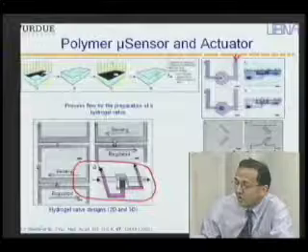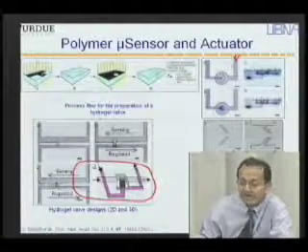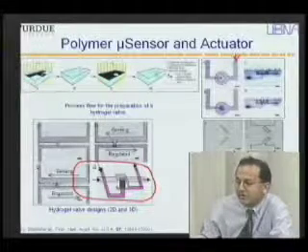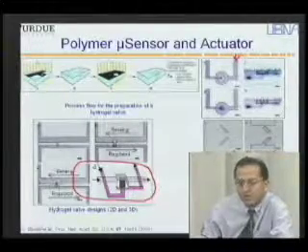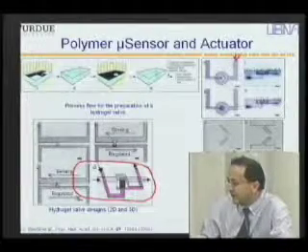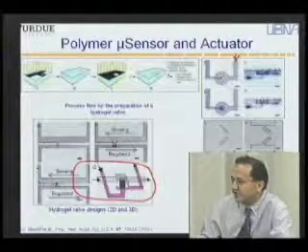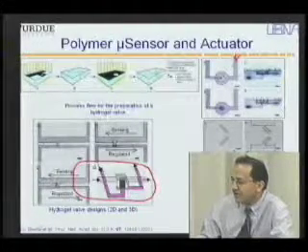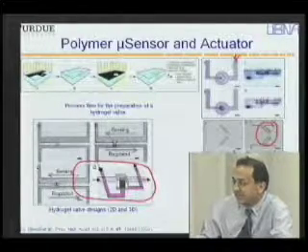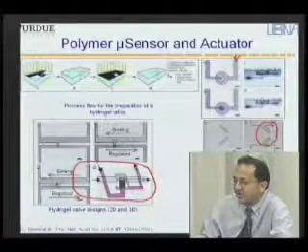An example here is this biomimetic valve using a bistrip hydrogel. So you have these hydrogel layers, these flaps right here that can swell, and as they swell, they close. They become a one-way check valve where the fluid can only flow that way and cannot flow back. And when you change the pH back to the normal value again, these polymers can shrink back, and the fluid can flow through in both directions.